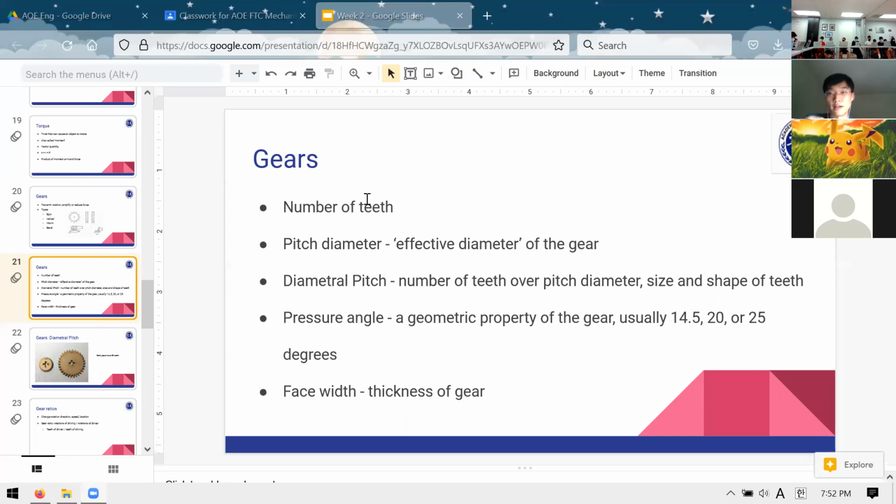And depending on if you're using metric or standard gears, it might be called something like module. So module or diametral pitch, or maybe just pitch, and pressure angle. Those need to be the same for the gears to work together. If you go and find CAD models on McMaster and you pick gears with a different diametral pitch or a different pressure angle, they're not going to mesh.